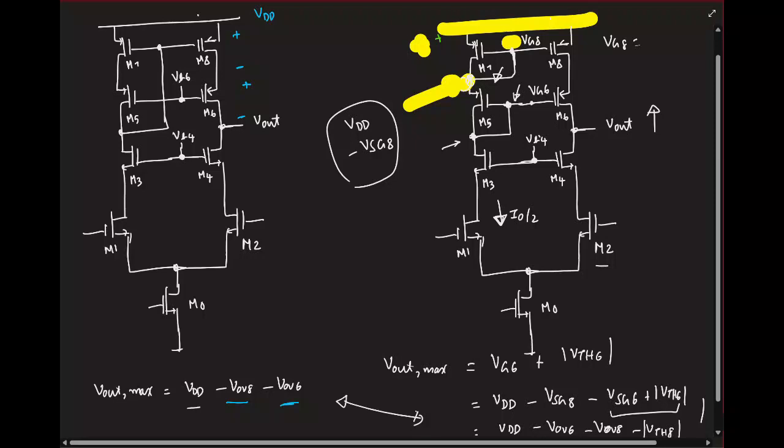So although the gain you will have here is same, the swings will be even limited in this case. And for this reason, this configuration, which I am showing in blue, is also called high swing cascode. Because this is also another cascode, what we have in the right, but the swings here are much limited. That's all.